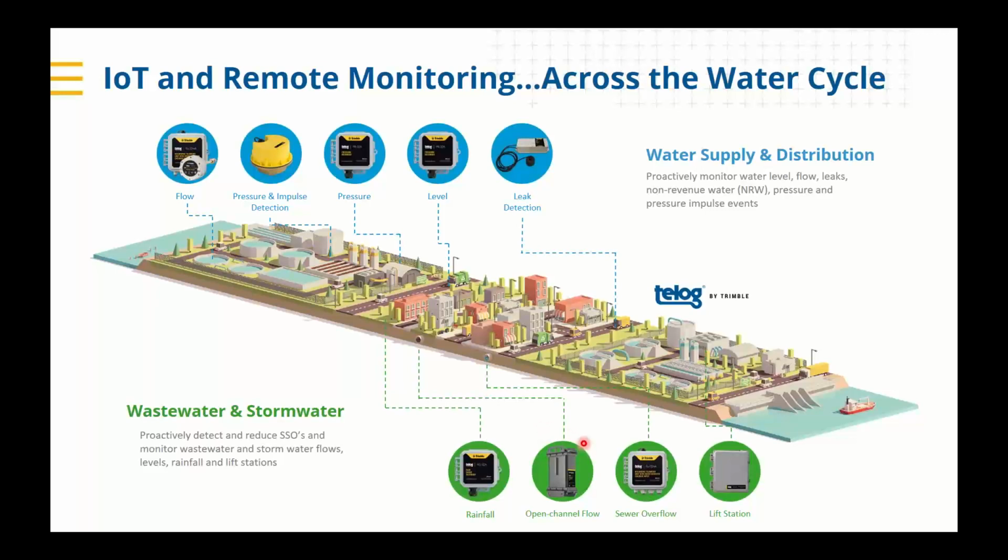Studies that are conducted for either I&I, capacity studies, hydraulic model calibrations, pretty much anything to do with studying a sewer system, we have a solution for that. As mentioned, we can get into sewer overflow studies and monitoring with a couple of different devices. And if you guys are monitoring your wet wells, your lift stations, your pump activity, we have a solution for that too. We have an RS system that is AC powered or battery powered that can slide right into there and accept different systems and signals from all your solutions out there.